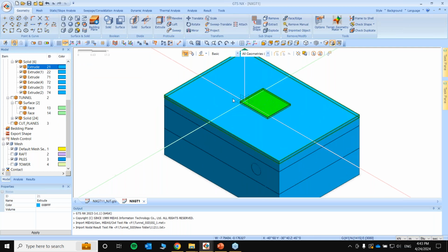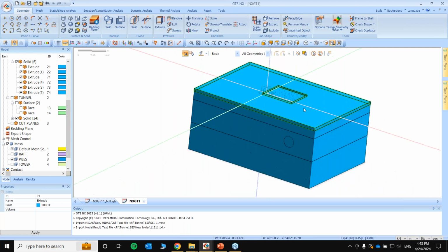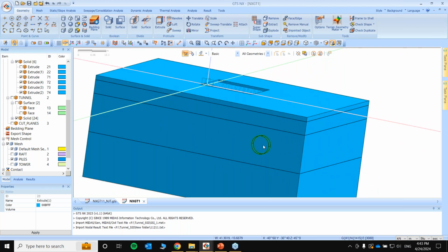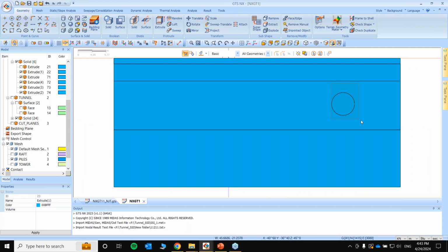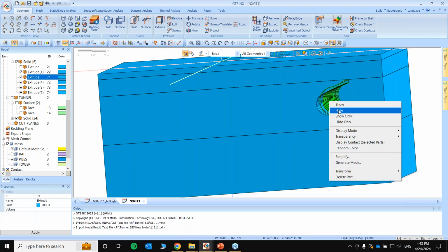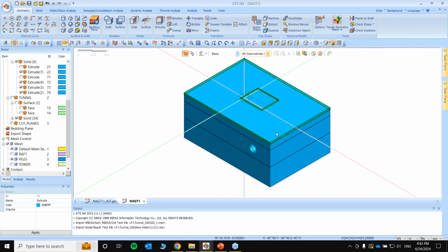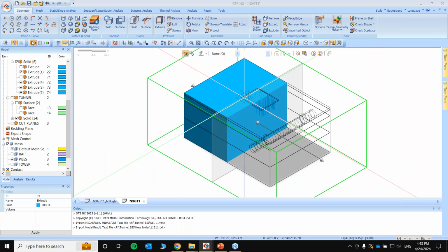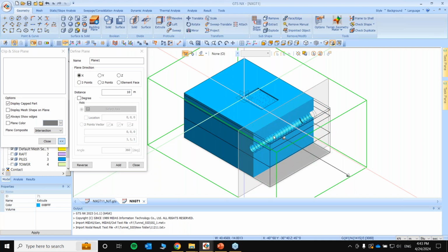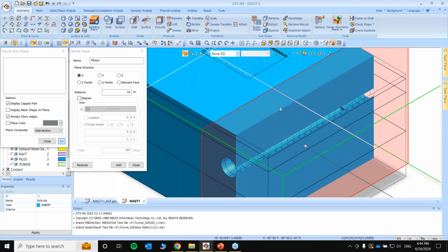So you can see area for my raft, sorry, cushion, has been created. Similarly, I hide this. You can see if I hide the tunnel sections and hide the grouting area too, you can see how the ground inside looks like. Or just to make it more clear, I can use the clipping plane option and see here, okay, that the solids are now connected.